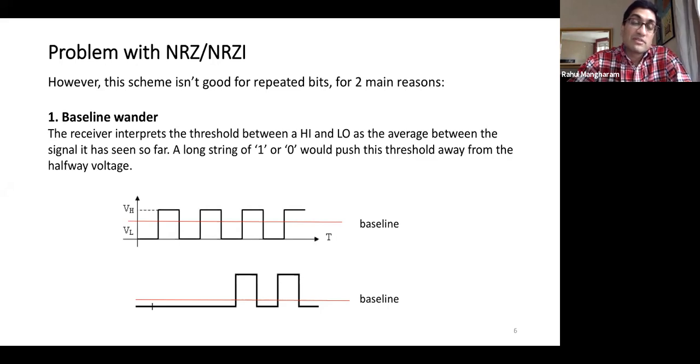Again, the main problem is that we have only this signal to provide us timing, but we also have only this signal to provide us what is a good comparison of what's a high and what's a low. I can't generate an ADC input and say, hey, here's 2.5. Then you can say, how about I just permanently generate 2.5 volts on the receive side and keep comparing to that? If I even run that comparison, I won't be able to keep up with this rate over here, right? So we can keep taking that argument forward and saying, how about I make this comparison really efficient? Then I say, yeah, then definitely, sure.